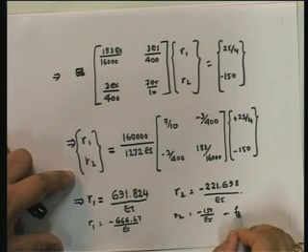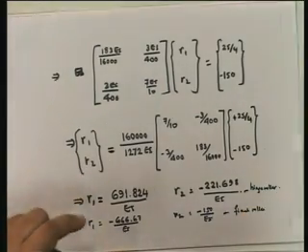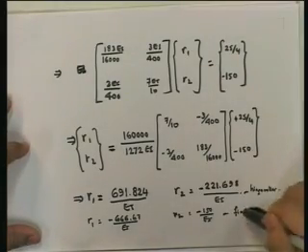That is when fixed roller. This is hinge roller. So now let us look at the effect of removing the fixity at this point to make it into a hinge, in other words, eliminating the rotational restraint. What has that done to the actual displacement of the structure under the same loads? The loads for both structures are identical, and the geometry is identical. The only difference is that in the previous case at C you had a fixed roller, and in the case we are dealing with right now, it is a hinge roller. So all we have removed is the restraint of rotation, and see what that has done to the displacement shape. It has had a significant effect.